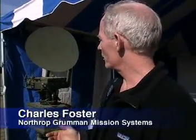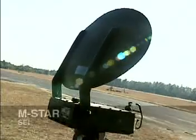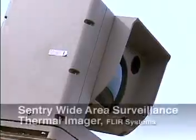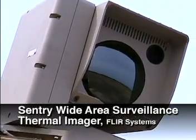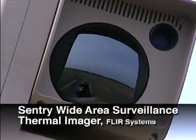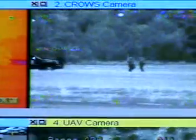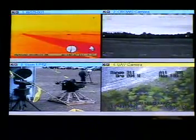What we're pulling in here is a new class of sensors, long-range sensors. This particular device, SEI M-STAR sensor, it has a 42-kilometer range. It will then, through a queue-to-slew capability, relay data to the wide area surveillance thermal imager. We automatically point this imager to the target. We have also integrated a remotely operated weapon system called CROWS that can effectively bring fire to bear on the target once it's acquired. As soon as the ground tracking radar acquires an enemy on the perimeter, it'll send a signal to the CROWS in the direction of the target.